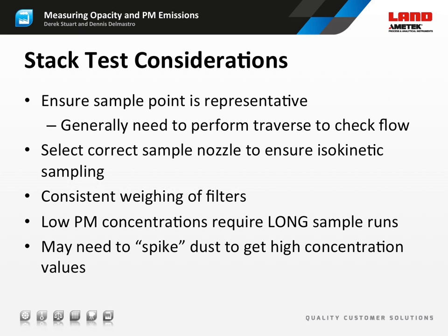There are some important considerations for a successful correlation test. The key thing is that the sample points for both the PM-CEMS and the reference method need to be representative. That is to say, the PM concentration and size distribution has to be the same for both of them, and they also have to match those in the stack as a whole.